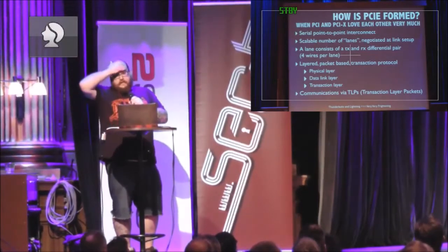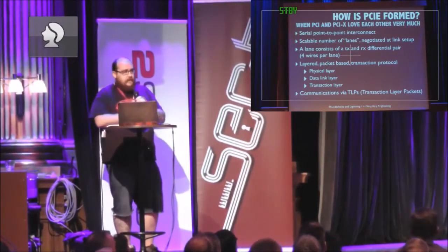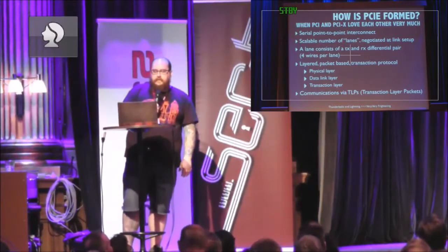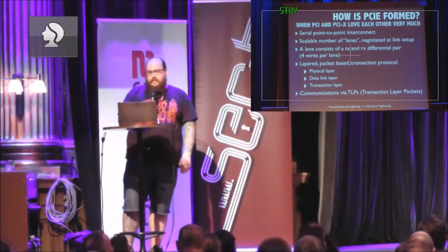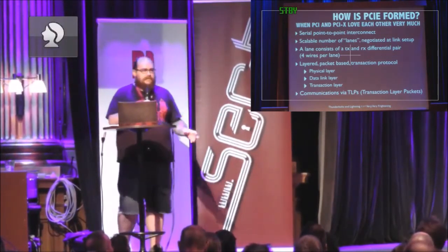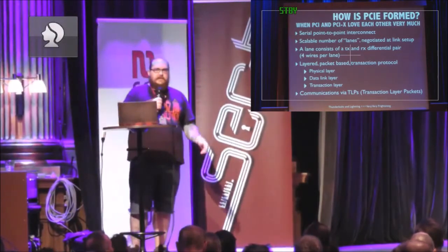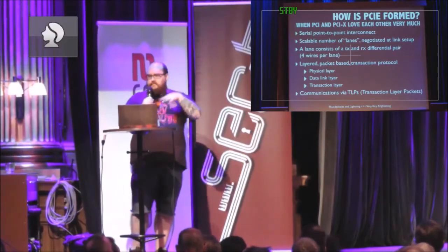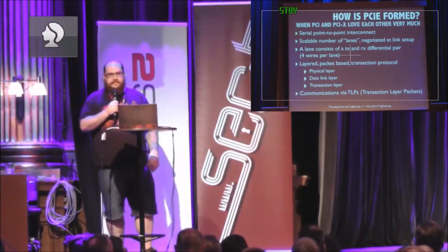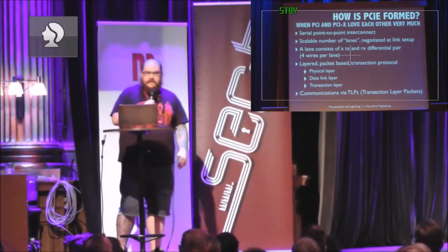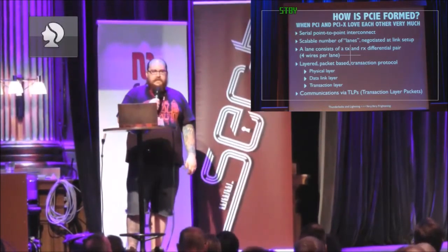So, now I'll dive into PCI Express a little bit, because that's probably pretty relevant for how all of this works. This is Sam's stuff that I have no idea about, a lot of it. PCIe is the evolution of PCI and PCIX, but it's not also like PCI. PCI had everything connected to the same bus topology, and PCI Express is everything point to point. So it's a fast, high speed serial point to point interconnect with a scalable number of lanes